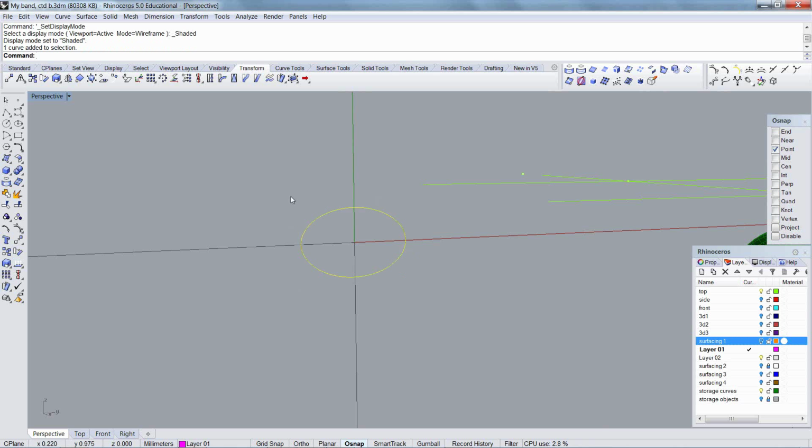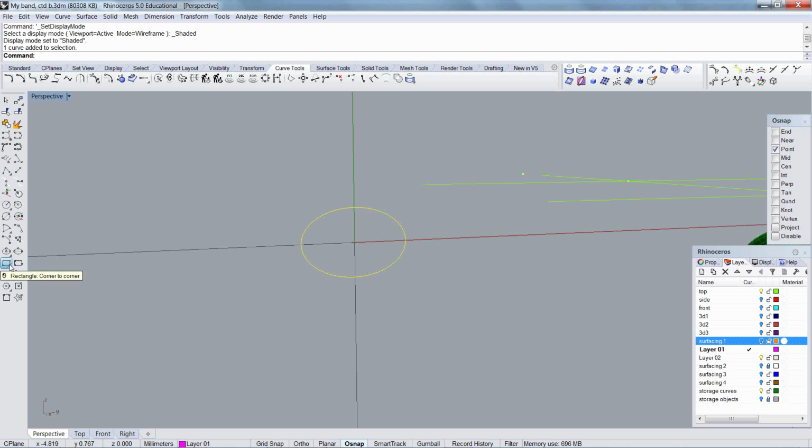I'm going to create a square or rectangle around this shape. There are a couple of ways to do it. Let's try rectangle, 3 points. Quad, quad, quad will not do it. So let's try from center. I know that won't work either. So I'm going to draw it directly.